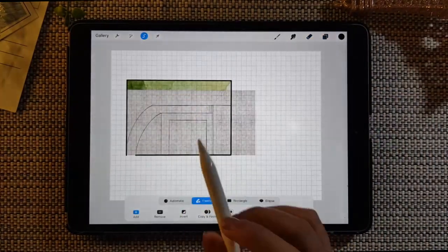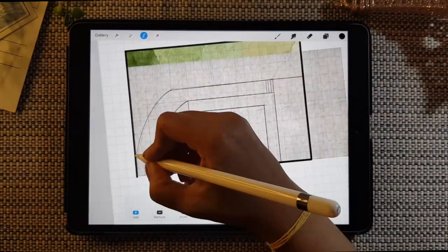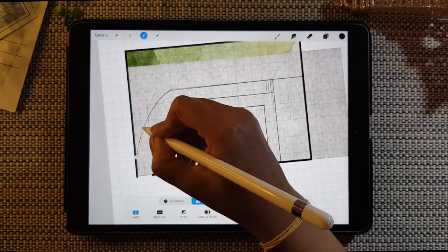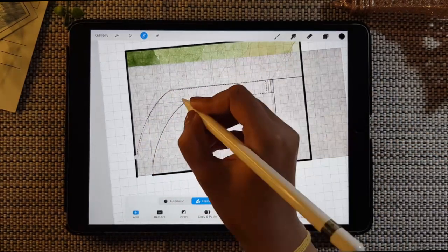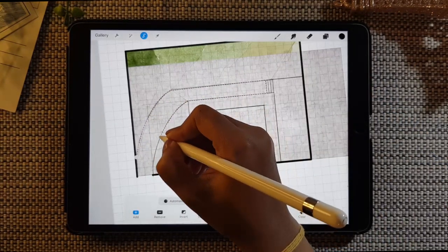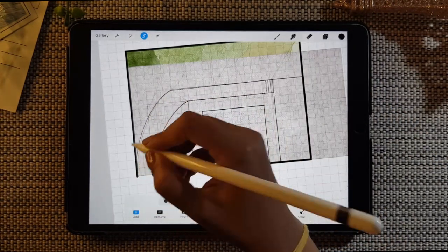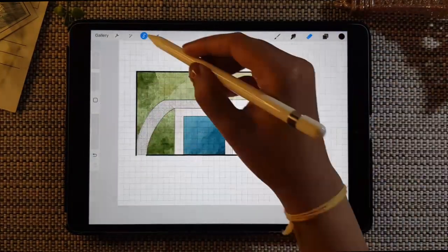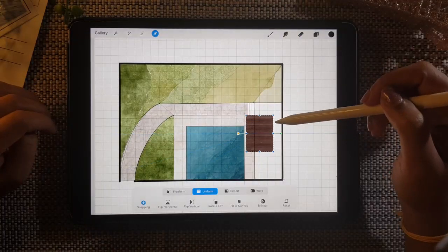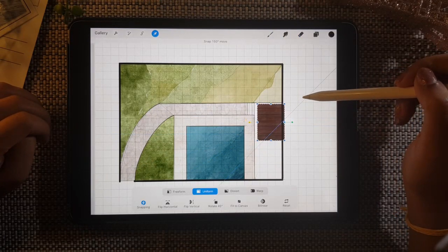So you need to think about how many stones would fit within 1 meter. If you have a better texture with smaller stones, then you can extend it and use it, no problem. But if not, then you can duplicate the layers accordingly and use the textures.